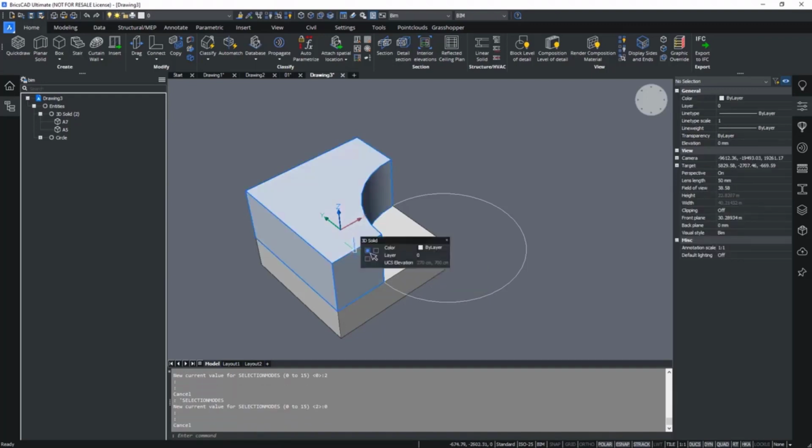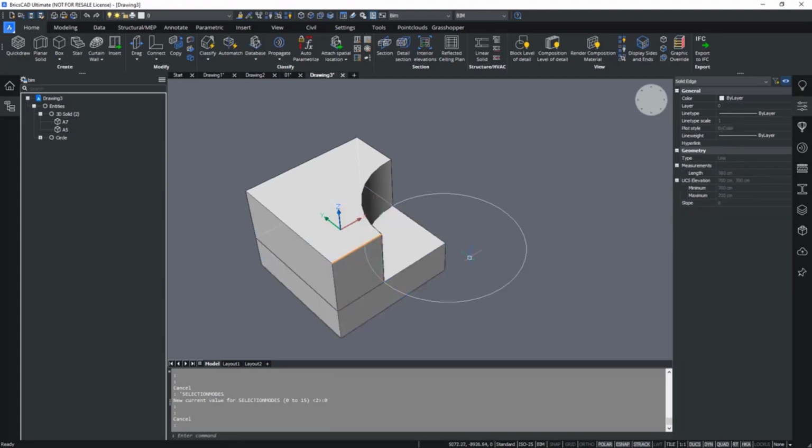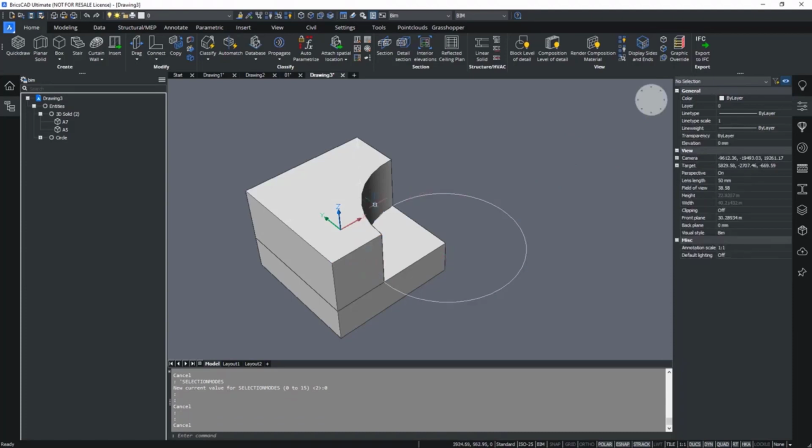And then you know the solid is selected. For an edge, if none of the faces or edges is prioritized, you can still hover approximately over the area of the edge, and hold down Control, and then you will also be able to select the solid edge. The edge selects in green, and when it's selected, you will see in the properties panel that the edge is selected.